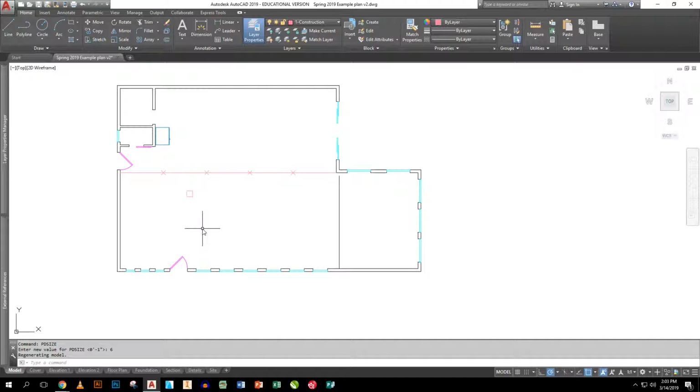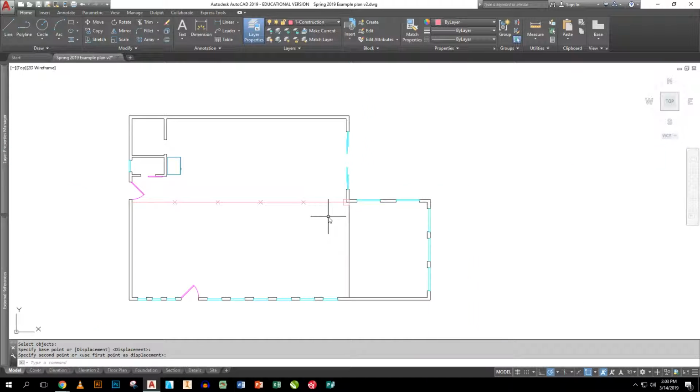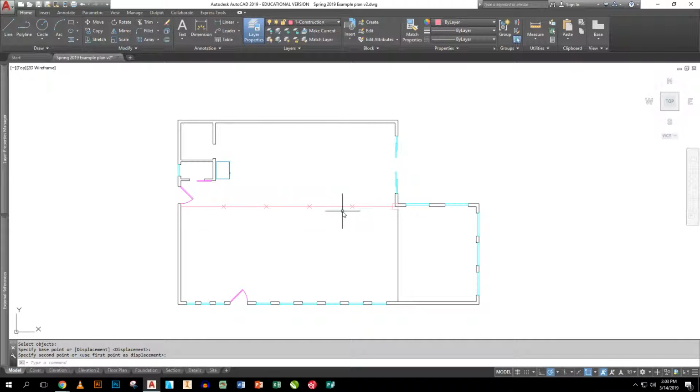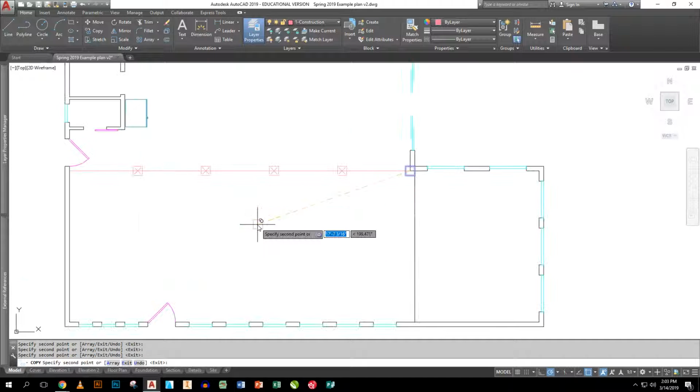So there's my points that I'm trying to hit. Now, if I move this rectangle I made down here, it's going to be embedded in the wall. It's probably actually a false timber here if I was doing this. But I can line it up, see it lines up dead center on that. I can go now with my copy tool from here, and I just snap to the center of that, bring it out to this node, and then this node, then this node, and then this node. So it evenly spaces them out, and I have it right down the middle of the house.